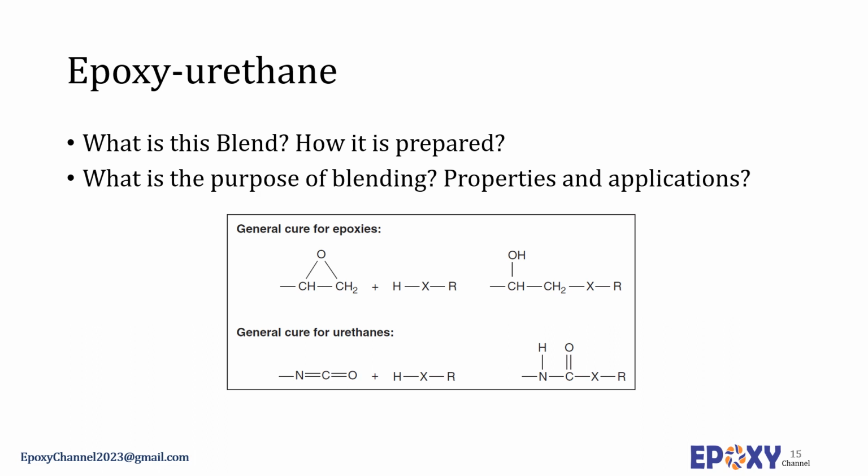An acrylate-terminated polyurethane modified epoxy compound and a polyethylene polyamine homologue and fatty acid combination were formulated into a two-component adhesive system. The adhesive is useful for bonding various thermoplastic resins such as ABS, polycarbonate, PBT, PC blends, and PPO.